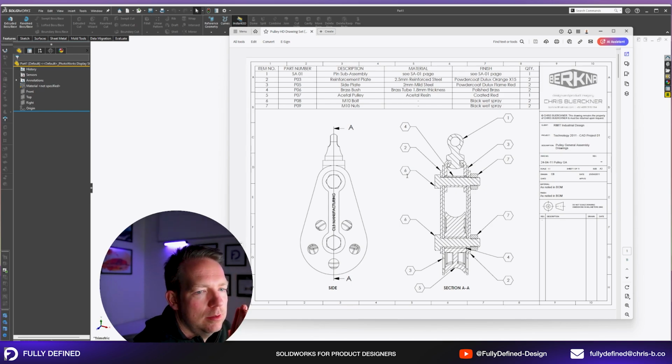Look, when I'm doing it, I keep it pretty straightforward. I'm looking for something that is going to be in the center of my product. So either a front plane or top plane or right plane is going straight through the middle. Usually I'm designing symmetrical objects, so that helps a lot.